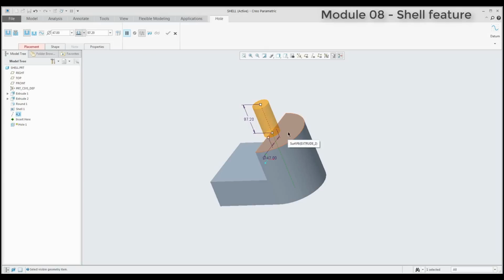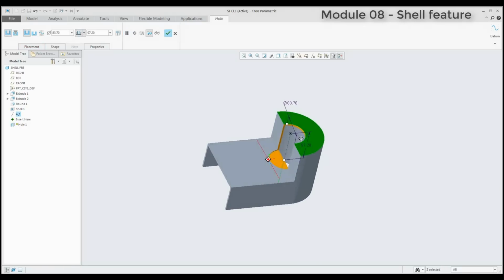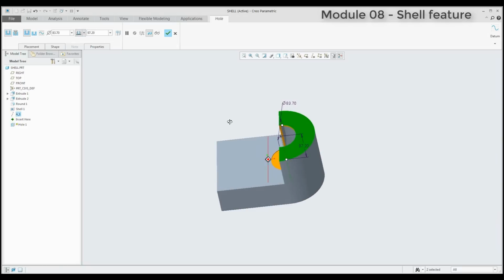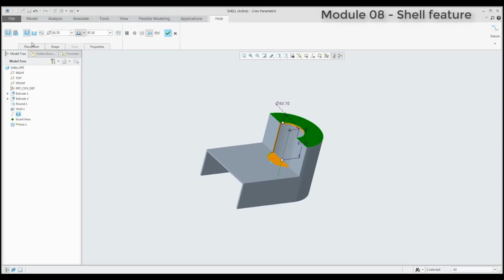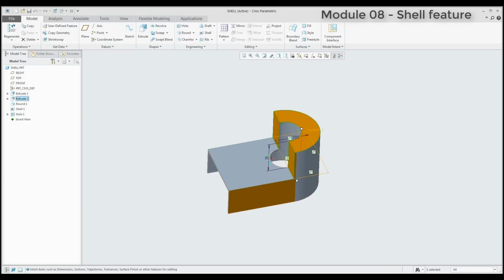With the control button, you will select the start surface, and the system will create the hole feature for you. Right now you can see that the system created everything correctly. I need to specify the depth, and the depth will be through all. So right now the system will go through with the hole. If you need to change the shape of the extrude tool, you can, with dynamic preview, again, really easily change it.